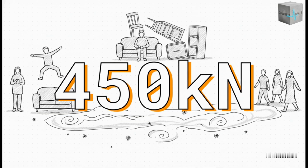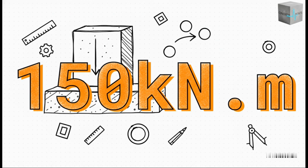Next, we add the live load. This is all the variable stuff. People walking around, furniture, snow on the roof. Here, we're looking at 450 kilonewtons. And finally, we have that tilting force we were talking about, the service moment. It's coming in at 150 kilonewton meters. These three numbers are everything we need to get started.